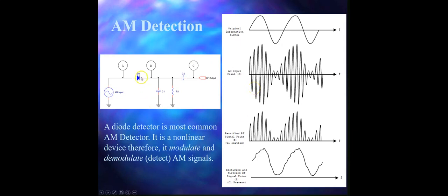Now here, the rectified waveform from D1 is passed to capacitor C1, whose role is to charge up to the voltage of each positive peak of the rectified radio frequency signal. And then we have the resistor R1, also called a bleeder resistance. If we didn't have R1, C1 would just charge up and hold the highest possible DC level.